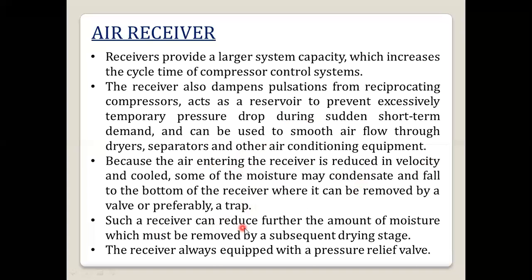Okay, so in this receiver we can reduce the amount of moisture which must be removed by the drying stage. If further moisture is left, it can be removed by the drying stage. The receiver is also always equipped with a pressure relief valve. We require the pressure relief valve because if the pressure in the air receiver exceeds the limit, we can release that excess pressure with the help of the pressure relief valve.